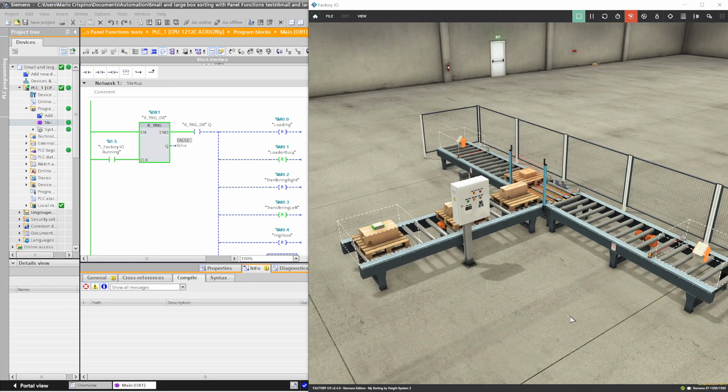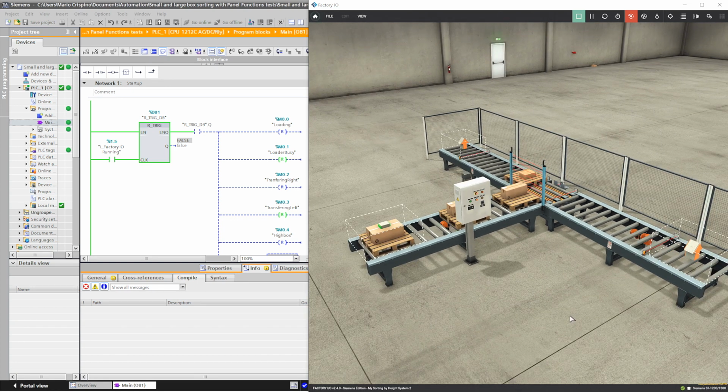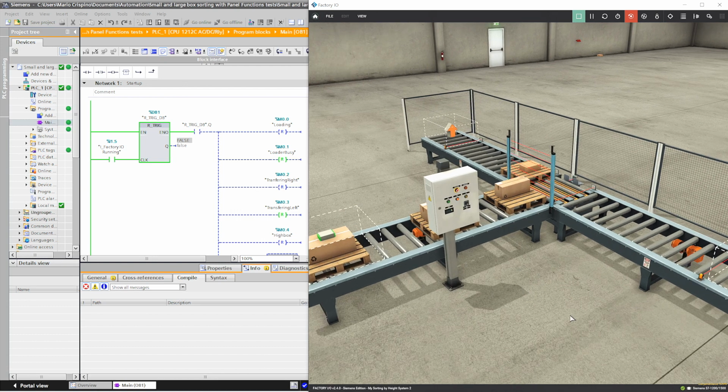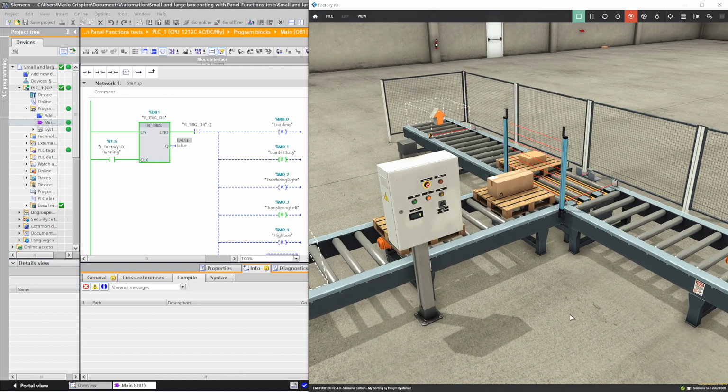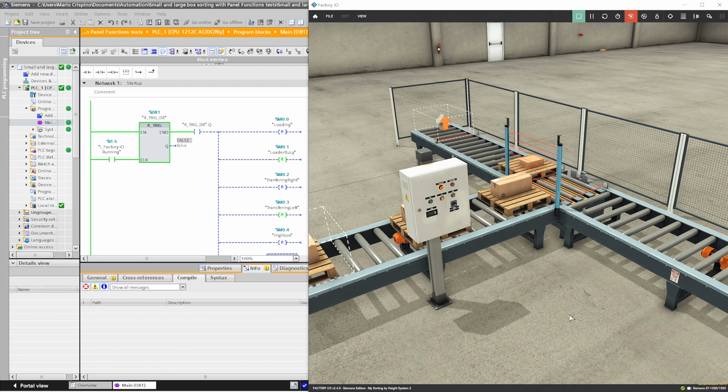Let's come out a bit wider to see if there is anything else on the right conveyor. That last particular pallet and box must have exited. Right, let's zoom back in a little and get ready to restart the system again. Now the procedure is as it was with a normal stop selected. However, when we disengage the emergency stop, the red light still flashes until the selector switch has been toggled, after which we can restart the system by selecting the green start button and everything should continue from where it left off. Here we go.